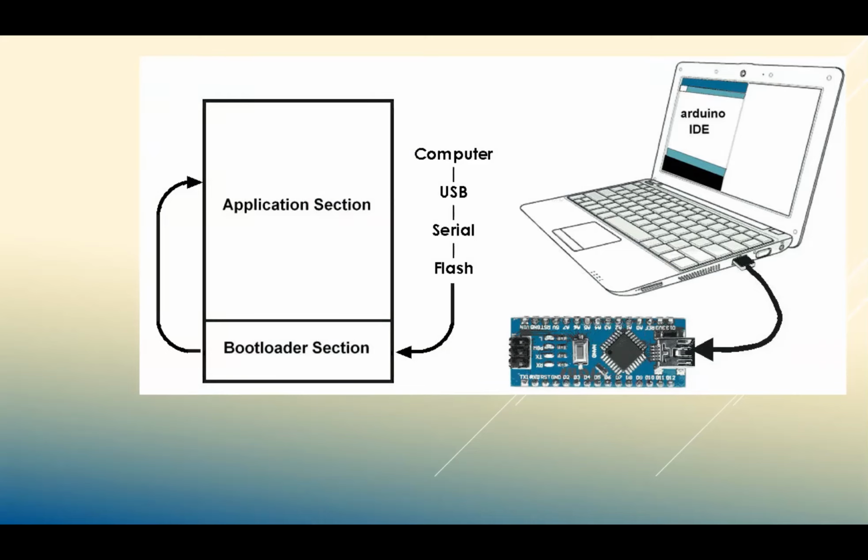And although it's smaller, it still sits in that 2K section. So although it's faster and smaller, we can't recover some of the bootloader section. And that's why the earlier spec, one said half a K and the other said 2K. They were both correct in that sense. So now we know what the old bootloader and the new bootloader is about and why you make those choices.